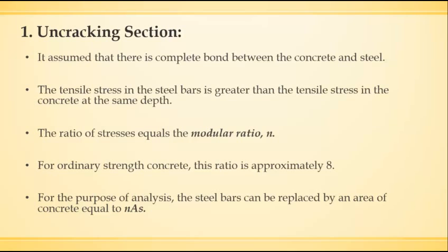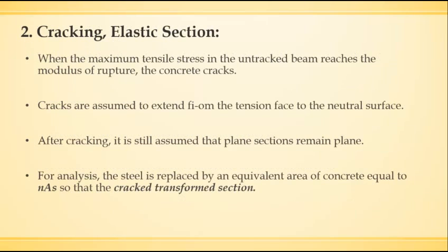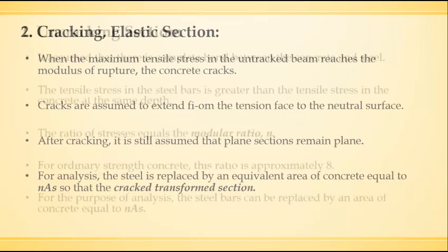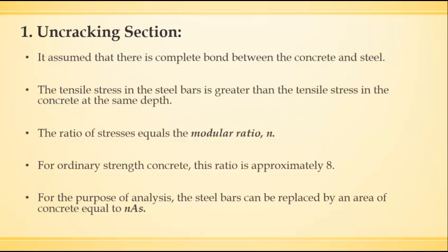For the purpose of analysis, the steel bars can be replaced by an area of concrete equal to nAs. The stress in the steel is n times the stress computed using the bending formula, with a value of y equal to the distance from the neutral axis to the depth of the steel.